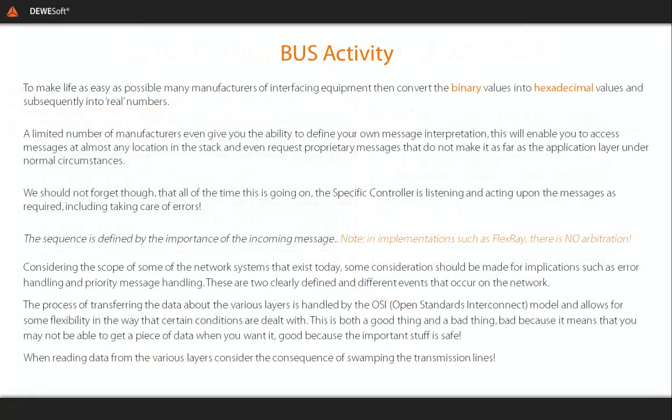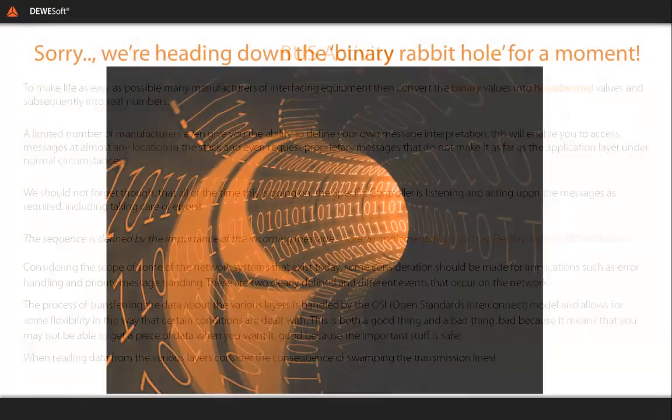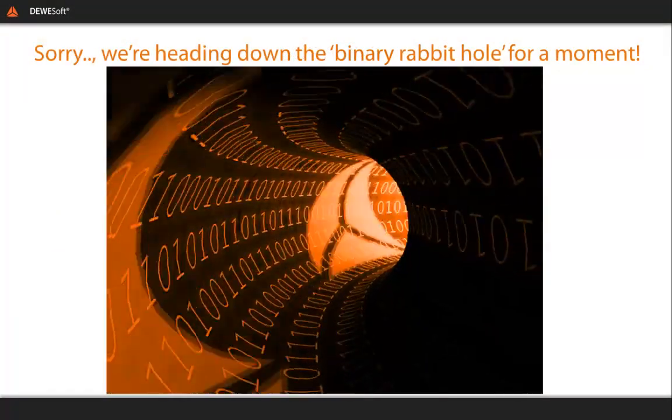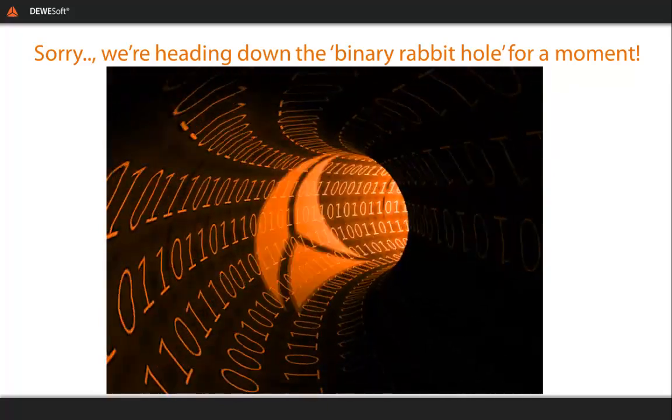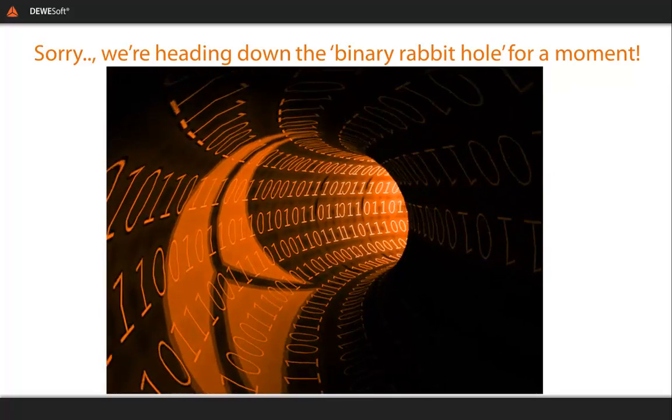Now, the active, passive, aka dominant and recessive components are the critical factors in CAN activity that determines what communications are taking place at what point and which will ultimately be made available on the bus, or as it's often referred to, get control of the bus. Now, we've alluded to it but not elaborated on the outcome of the dominant and recessive parts, as well as how ultimately we get the information that is made available.